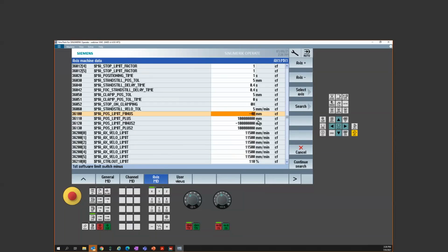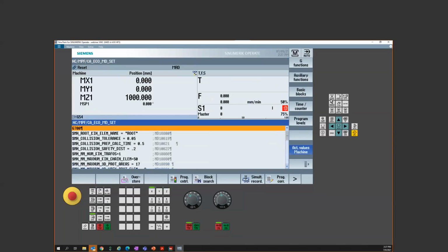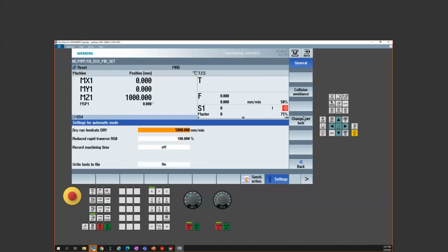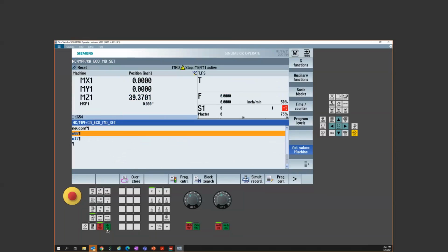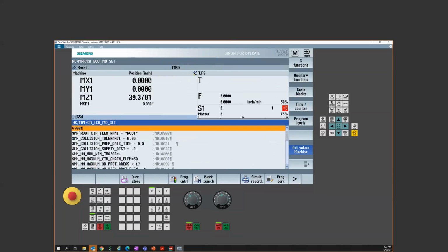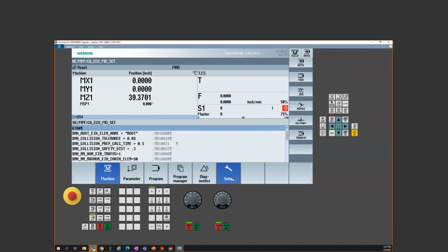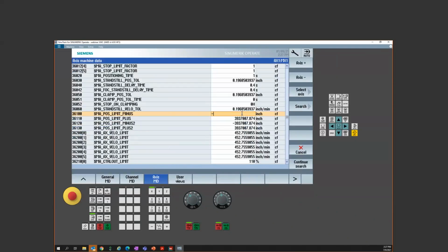See, it's in metric. So I do want to change my unit of measure, because these machines power up, and I'm going to have to actually rerun that program. I forgot to change the unit of measure. These template machines initially power up in metric, but I figured we'd do this event in inch. So let me rerun that one more time. Now it did have the unit of measure here, so I've probably been okay, but I prefer to make sure I ran it while I'm in the appropriate unit of measure of this part program. I'm setting a lot of machine parameters, so it could get a little funky on me. Now we can do the real travel, and this way it won't convert the numbers to some little tiny number.